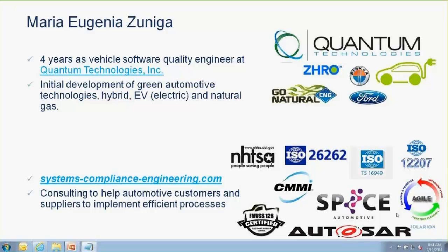We have to have windshield defrosting and fog systems to avoid crashes, recirculation of air to avoid carbon dioxide intoxication when all the windows are closed, cold temperature requested at startup in hot environments because you might have a heart attack, seat belts for babies, design reviews, material, etc. So it's a lot of information that needs to be processed.